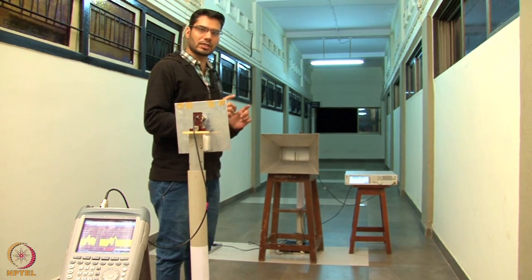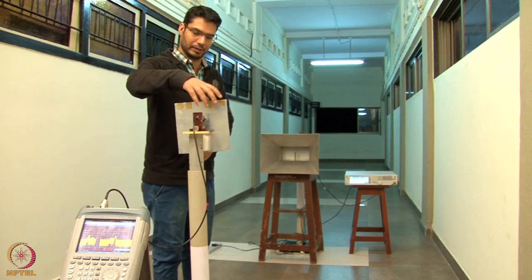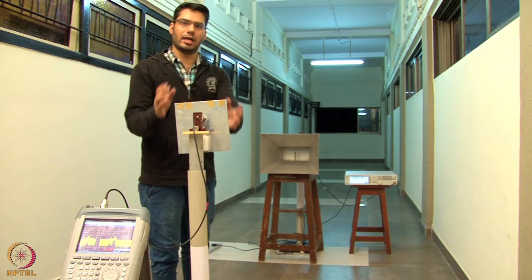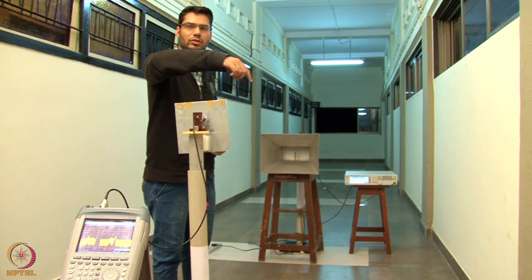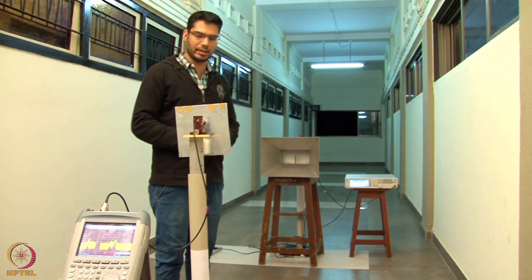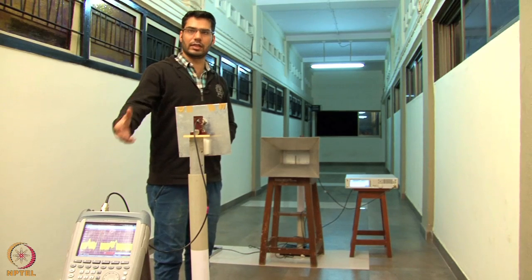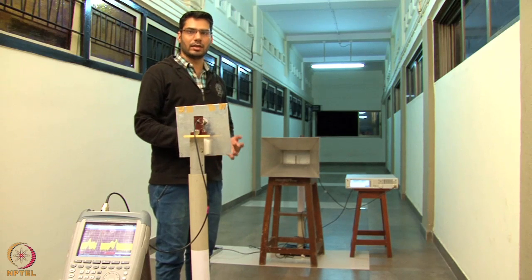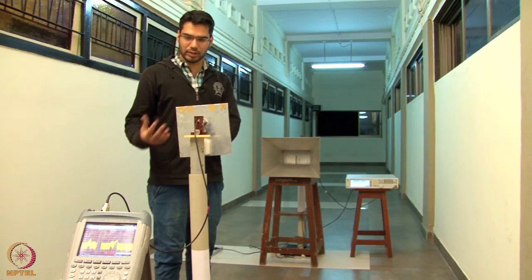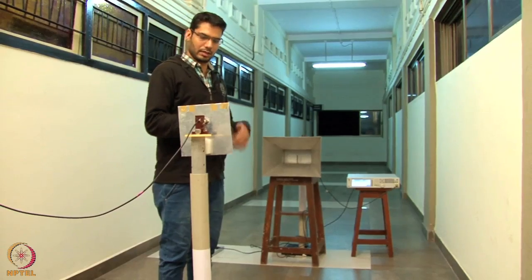If we want to measure the cross pole in the H plane, then we will rotate this antenna by 90 degree. After that, rotate 0 to 360 degree in the horizontal plane with respect to our reference antenna. This will give you the cross polarization components in the H plane. We will show you the demo for the E plane co-polarization components.